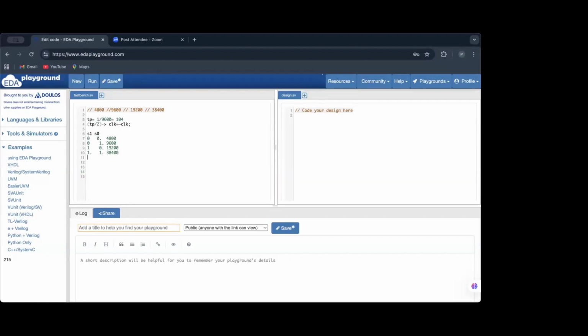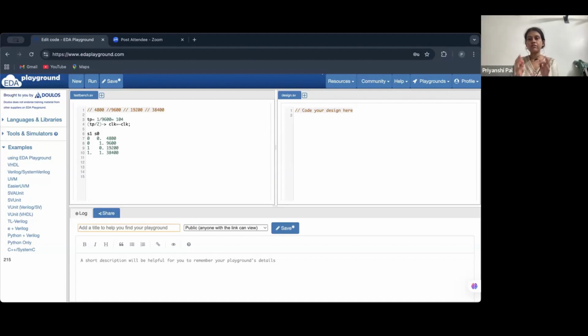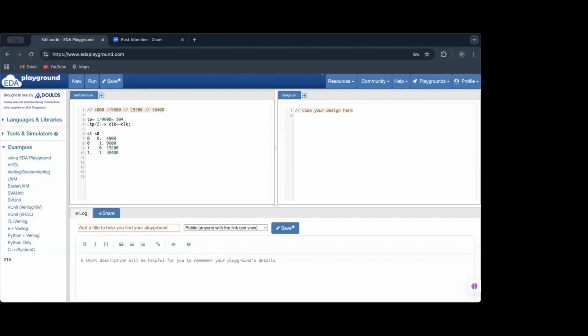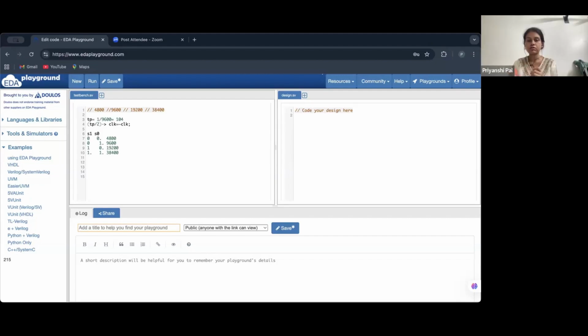So how is the data transferred in SPI? Ma'am, basically, we have MOSI and MISO. The LSB of MOSI goes to the MSB of the MISO, and here the LSB of MISO goes in the next clock cycle towards the MSB of the MOSI. Like this, serially, the data is being transmitted bit by bit.